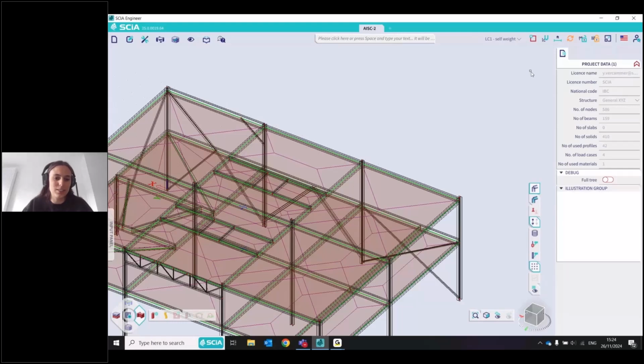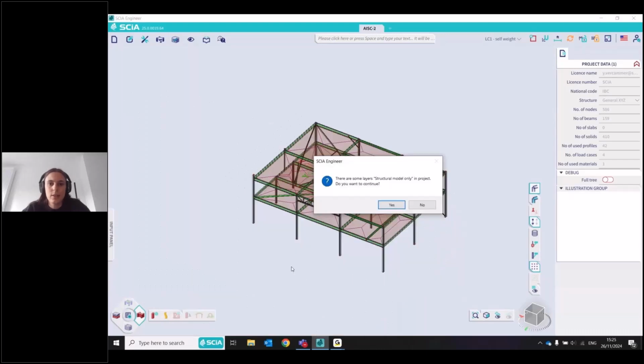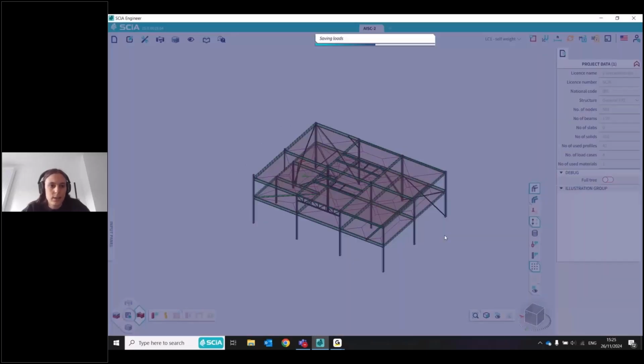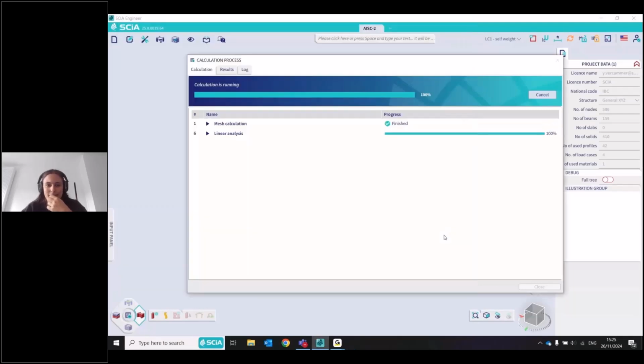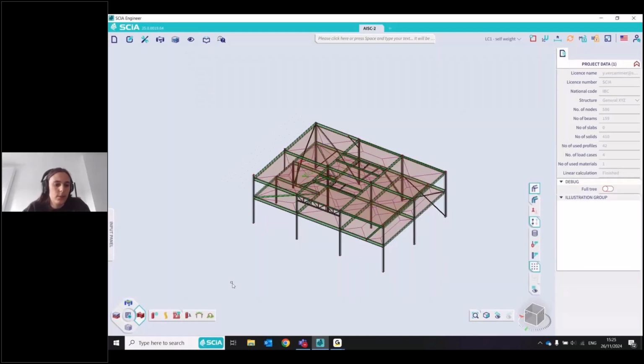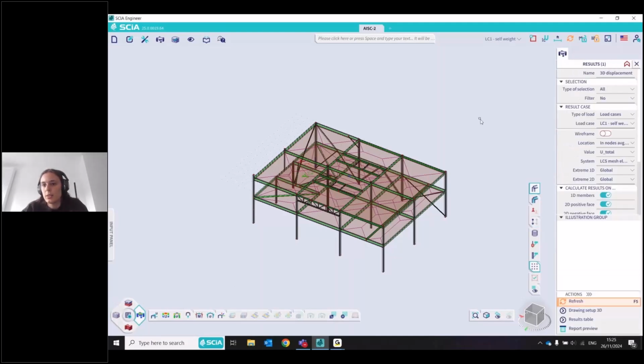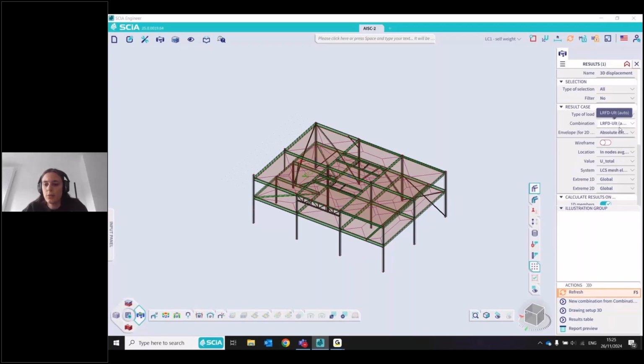So then the next logical step in our journey here is to calculate the project. This is also completely similar to anything else you would do for any other available design codes in SCIA Engineer. But yeah, I like to focus still on it. I think most importantly, when you first have modeled a project, is to go look at the result and look at the 3D deformations, because for me, this is kind of the best check for: did I make any modeling errors?